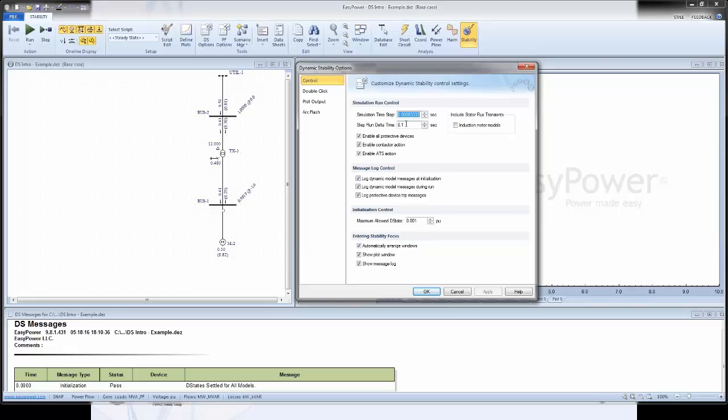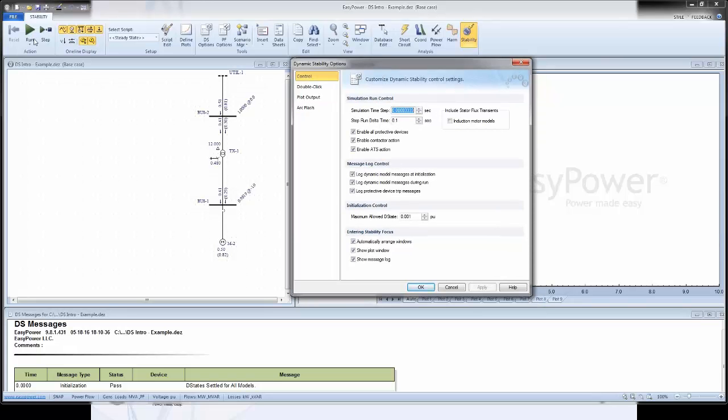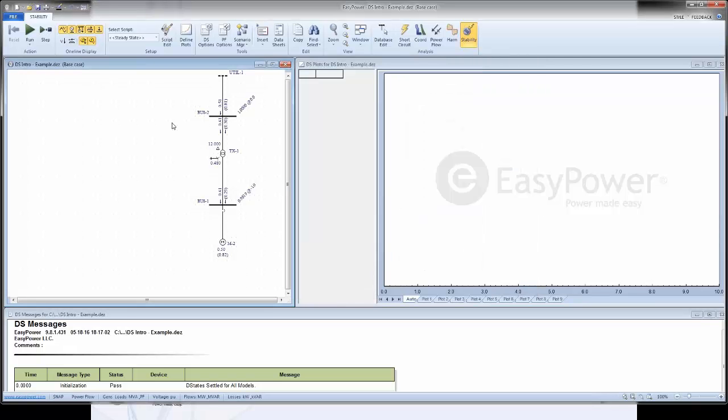This is an interesting option that I'll give you a brief explanation of, but we can certainly do more examples when I get there. You see this green run button here, and it has the capability of running the simulation, and then instead of seeing the whole waveform, it allows you to plot the waveform in these time steps that you define here. For example, if you say 0.1 second here, you can just click on this run, and it runs the entire simulation for you. Even though I understand it might be a little bit short, let's just give it a try here.